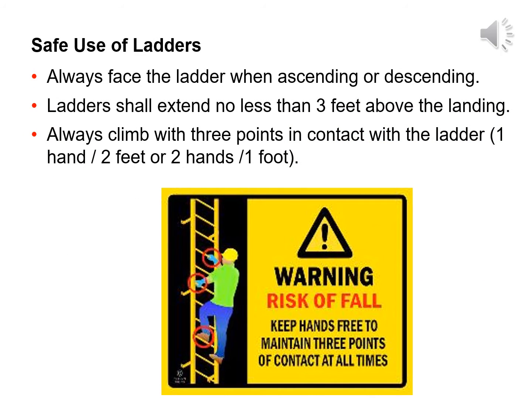There are several things to remember when using ladders. To use a ladder safely, you should always face the ladder when ascending or descending. Never carry tools or materials with you. Use a rope and bucket to haul them up after you reach the landing. Ladders shall extend no less than 3 feet above the landing.